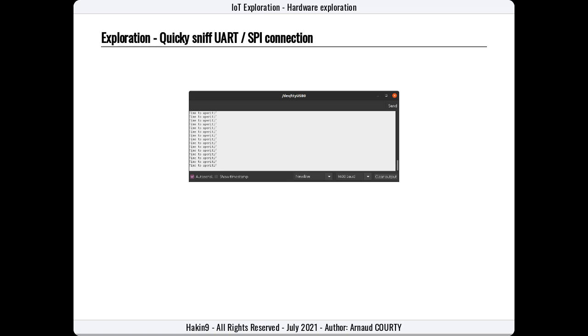By reviewing the DVID GitHub project, you have probably found that the Bluetooth device is connected using UART connection. The TX and RX pin are connected crossly between the Atmega and the Bluetooth dongle. After a correct probe installation and opening a serial monitor, you will see, as shown in the screenshot, some data on the BLE peripheral.